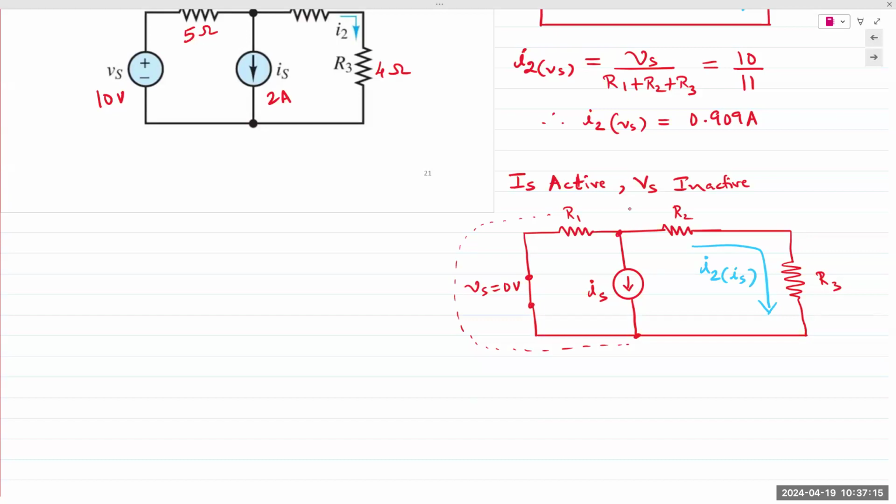Then you apply Ohm's law one more time, you find the current I2, IS. Make sense? Yes. Yes, we can. Question being asked is, can we do a mesh analysis? And the answer is yes. So once the initial setup of superposition is complete, you're free to choose whichever technique you want. But in this case, current division is like a one-step answer.